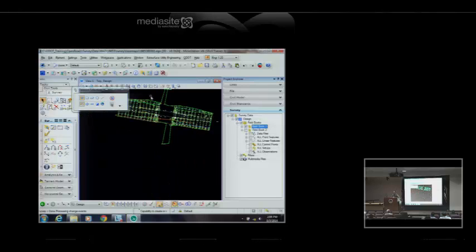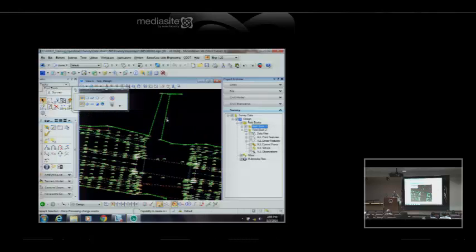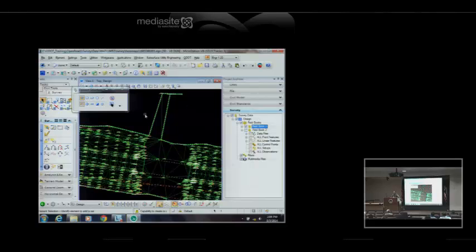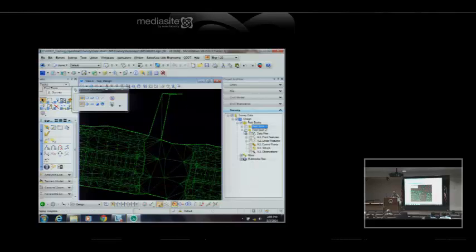So I cannot create a terrain model from a data set. I create a terrain model from a field book, so that was my mistake there. All right. So on this first one, I will tell it create terrain model. That is the underlying topo. I'll go ahead and change the feature to use the triangles. Okay. Off. Terrain's still going to display.